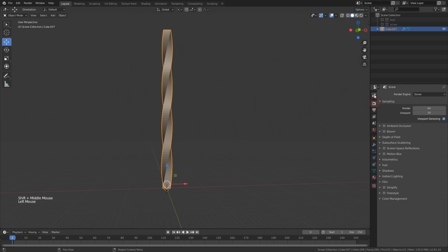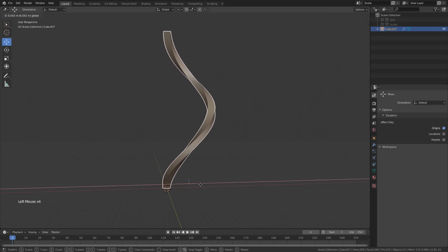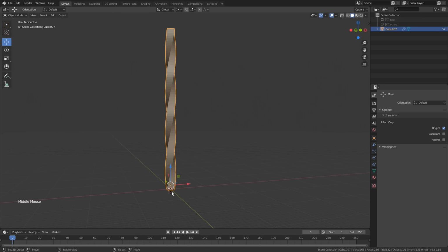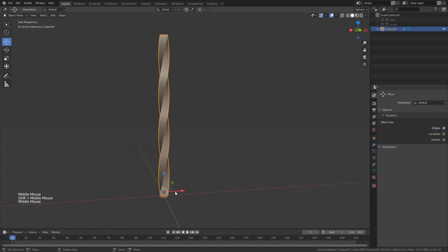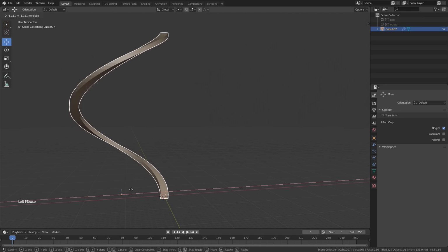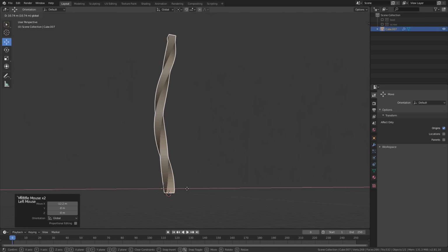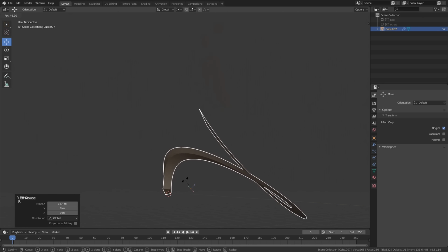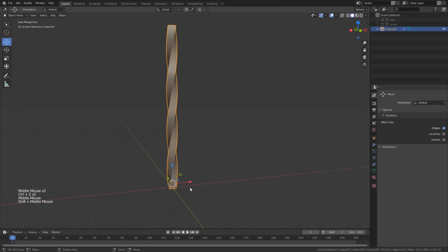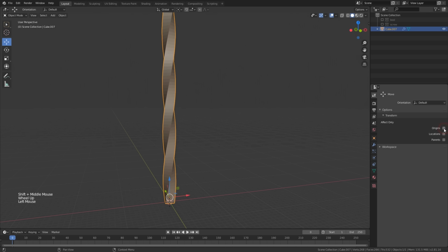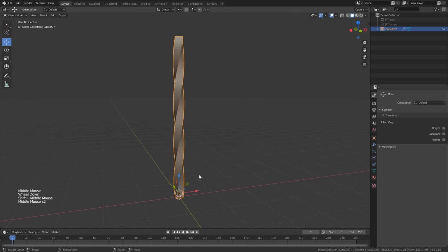Now if I go to active tool properties and change the origin of it, this twist modifier was taking the origin of the actual geometry. Now look at the way it behaves when I change the origin. Right now it's taking this point to deform the object, and I can even rotate this and create something very abstract. But every time it's not very convenient to actually change the origin of your object. There might be some other things linked to this object and it could break the hierarchy.